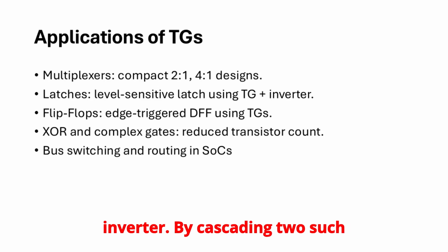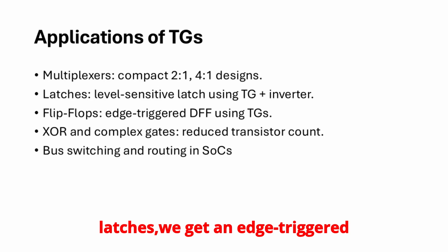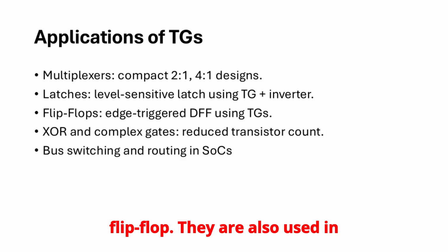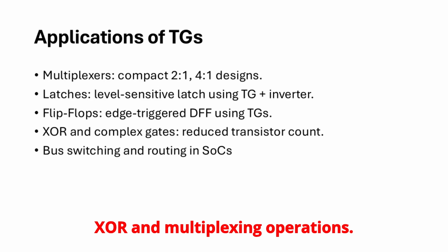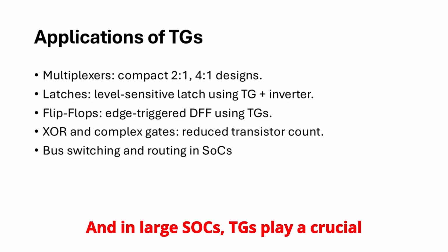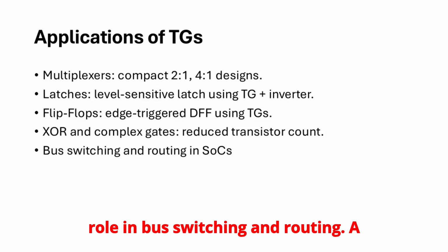By cascading two such latches, we get an edge-triggered flip-flop. They are also used in arithmetic logic circuits for efficient XOR and multiplexing operations. And in large SoCs, TGs play a crucial role in bus switching and routing.